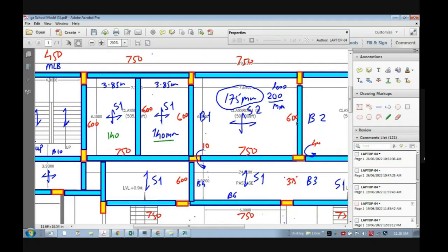As I already told you, you can control the bending moment values by giving continuity to the beams. So B2 पहले continuous नहीं था, single span था. Once I provide this beam, then it is a continuous beam, and once you give continuity to the beams, the bending moment will reduce and they will distribute uniformly among each other, and then you can control the depth of beam. Because see, depth of beam is decided by strength criteria, that is bending moments, and second is the serviceability criteria, deflections. So deflection or moment, once you control the deflections and moments, even deflection will reduce by adding